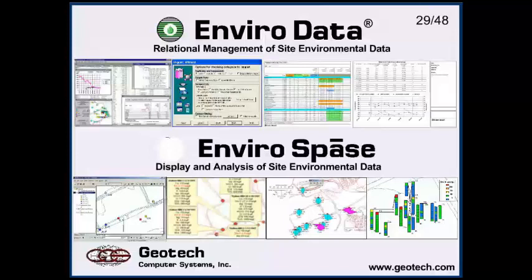So if, for example, you start pumping in chemical oxidants or bioremediation chemicals or something like that, you've got a general idea of where they're going to go. So the cone penetrometer, like I said, is mainly an engineering tool, but it's also used in environmental work to get an idea of the rock properties down below.